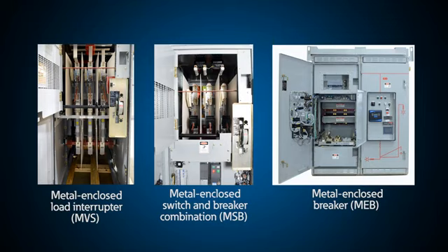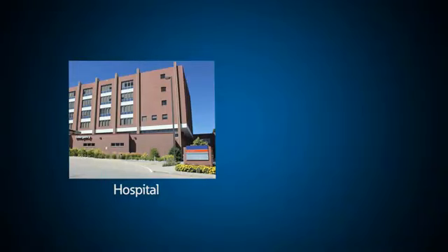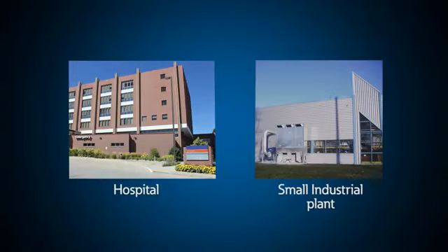Metal enclosed switchgear contains circuit protection devices including circuit breakers, power fuses, and fusible switches, as well as control and metering equipment. These devices can be fixed mounted in common compartments and do not require the separate barriers or compartmentalization required in metal-clad switchgear. Metal enclosed switchgear is applied in commercial and many industrial facilities where the rugged construction of metal-clad may not be required.